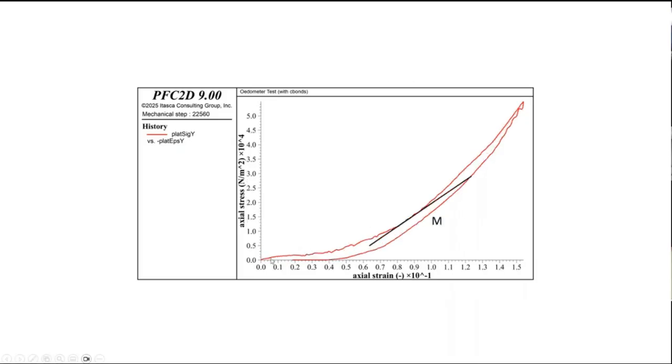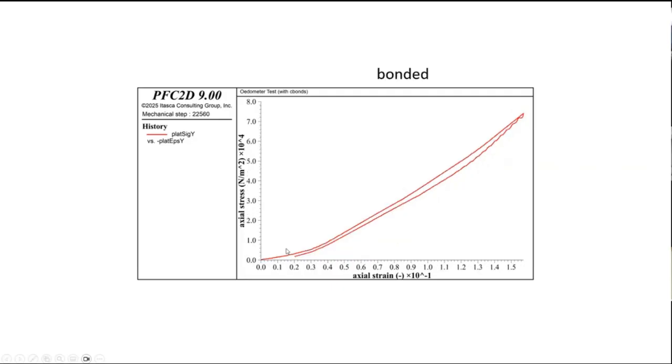Comparable, right? See, look at this. The stiffness is almost zero. The stiffness is definitely not zero. And then it much more quickly gets to be the same. This is because those initial gaps, we didn't put cement in those gaps. So they're closing up. And now pretty much it's the same. Nothing is really changing. That's why it's pretty much linear.